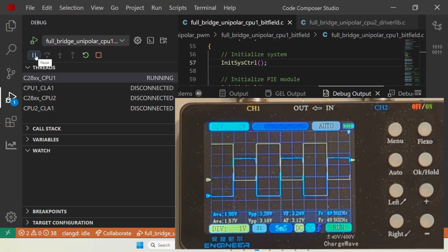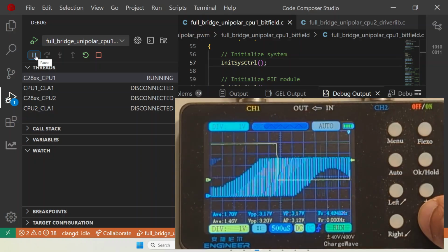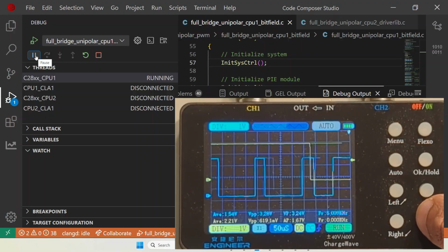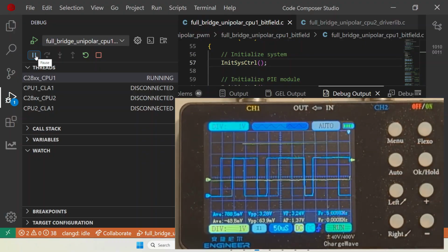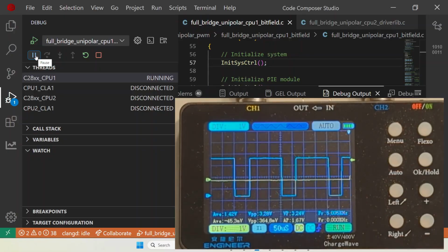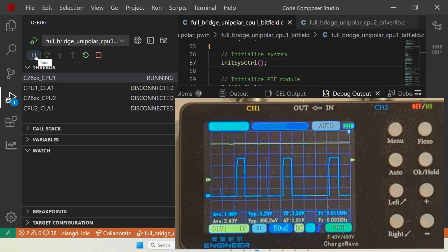At this point of time, let me go and connect one of them to S3. So you get, of course, what seems like a rectangular sinusoidal waveform, but this is actually incorrect. This is mainly because this oscilloscope doesn't have the resolution for this. So I will have to decrease it further. And you see now that we have this, it is gone. Again, this is actually very difficult to observe for the simple reason that we now have a 150 Hz waveform and the other to be a 5 kilohertz waveform.